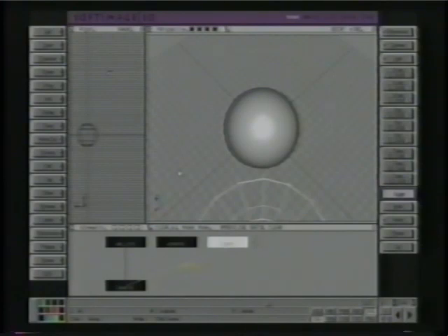Now later on, as you're working in your scene, this light won't constrain to the camera, it'll constrain to the camera interest and actually won't work. So one way we can get around that is make a brand new scene, for instance just like this scene, only without the sphere. Save it and then load it in on top of your other scene, and then if there are no animations on the camera already, this light constraint will take effect.